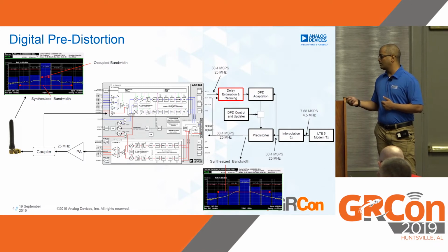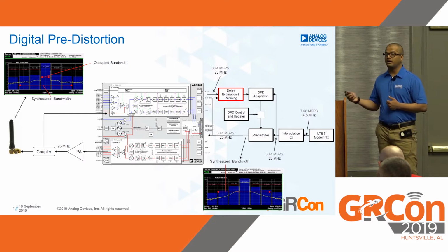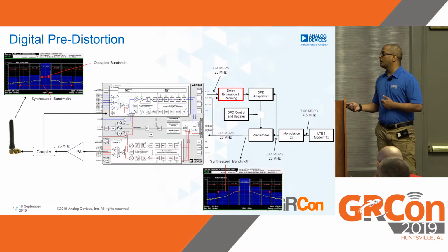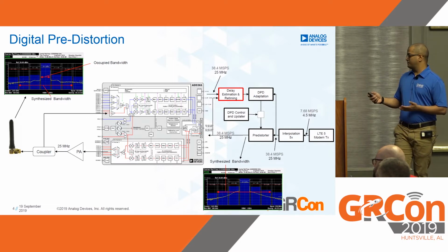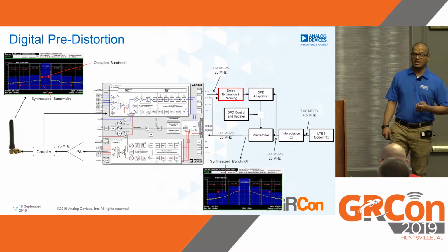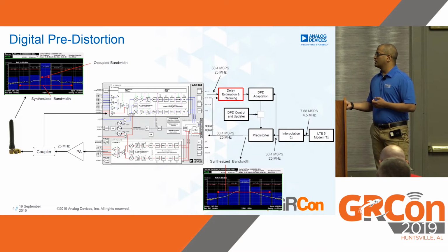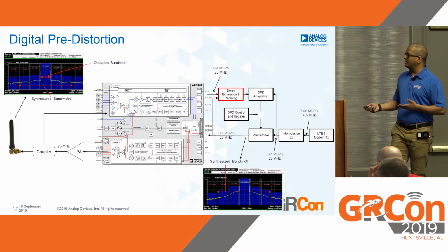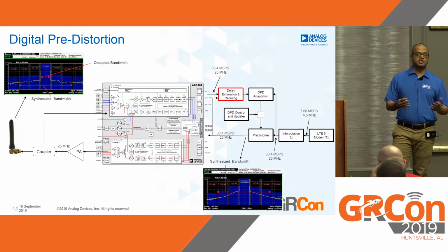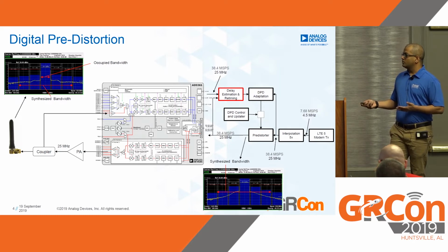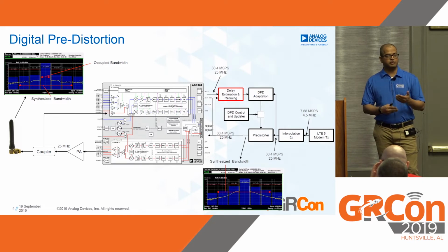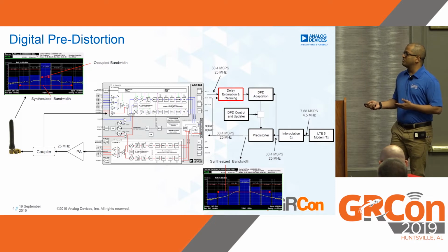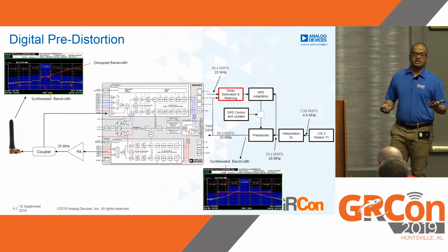So that gets sent to the transceiver and eventually to the power amplifier, and by way of a coupler, it is fed back to, say, the host PC or the FPGA on the Zynq SoC sitting in the RF system on module that actually implements the digital predistortion algorithm. So if we see here, the digital predistortion algorithm requires both the reference waveform and the received waveform, but they need to be aligned in time in order to do the DPD adaptation and actually linearize the PA effectively. Studies have shown that any mismatch in timing delay between the transmitted waveform and the received waveform results in suboptimal DPD adaptation, and the ACLR for the signal of interest is going to be insufficiently suppressed. We don't want that.